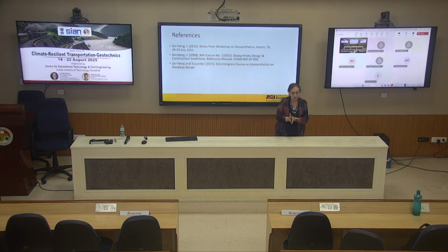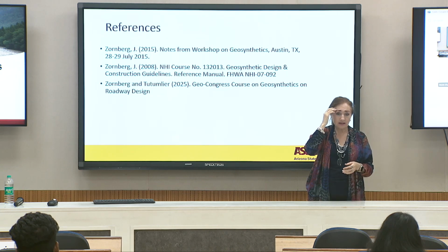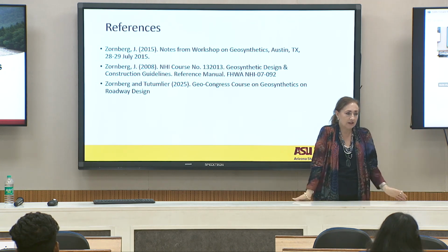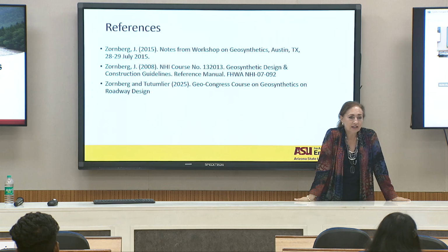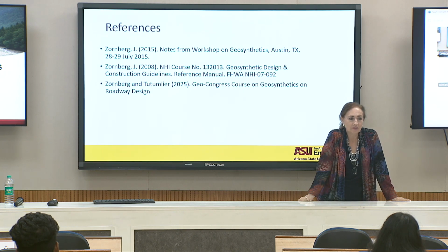So yes, there are some composite geosystems that you can do. Vertical drains always work, if you need to get the water directed to a certain plane. You can always do sand columns or stuff like that when you can get the water in. I think at the end of the day, it's not that we don't have solutions, it's which solution is most economical for you, right?